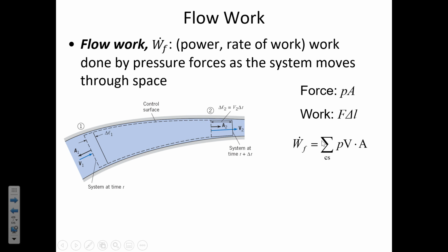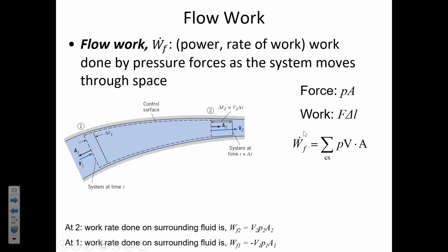And when we want to know the rate of work that's being accomplished, we then consider the velocity. So the velocity term has units of time. And so the fluid pressure multiplied by the area, remember, gives us the force. And then the velocity is some distance, the delta L, per time. So this W dot, the rate of work that's being performed by the system as it's moving through the fluid, is just the difference in the pressures upstream and downstream multiplied by the velocity.